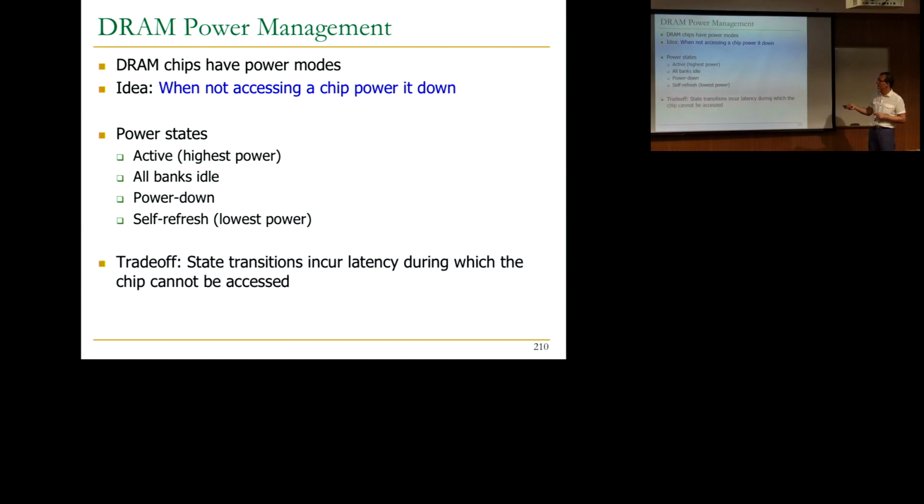But there's a trade-off because when you want to move from self-refresh to active, it takes a long time, on the order of microseconds, if I remember correctly, but this may also depend on the technology. So it takes about microseconds, and you cannot access the chip. So it may not make sense to go into the self-refresh mode if you're going to get out of it quickly. Right. So there are trade-offs here.